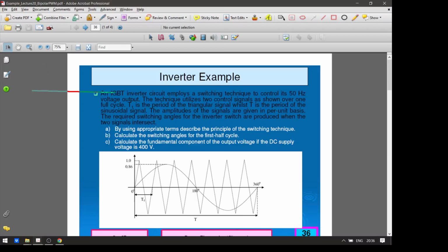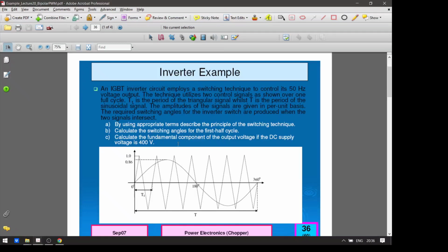So when you look into the harmonic spectrum of the PWM waveform, before that, we need to look into the PWM signals as well as the output voltage. This is only the original modulating and triangular carrier signals. So we need to observe the output voltage, then we can appreciate what a fundamental is.